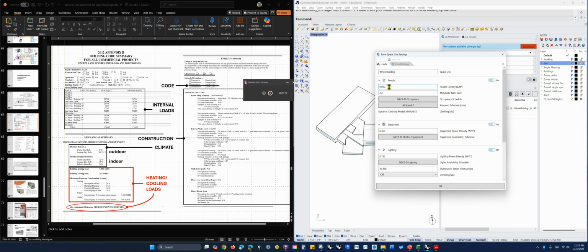So we could pick a different number. It doesn't matter right now, but I would stick with the one that you pick in a template. That's fine, that's where it's coming from. The metabolic rate is how fast people are moving around. 1.2 is a good default to leave because 1 would be completely stationary, essentially comatose. 1.2 is moving around, kind of office level. It's a good baseline.